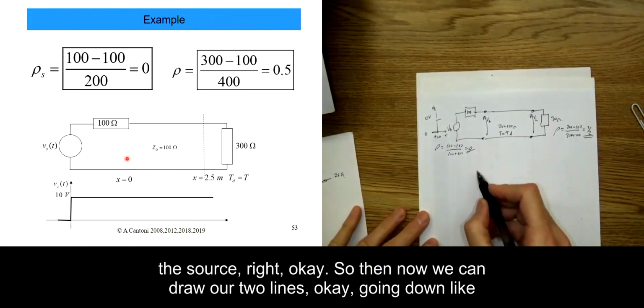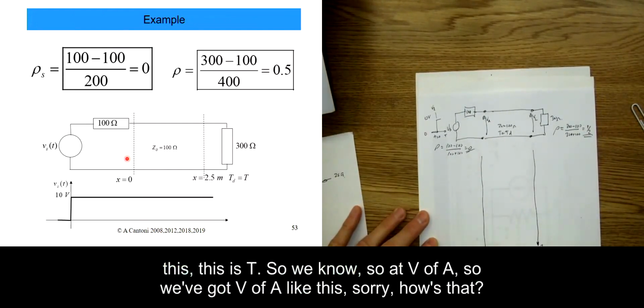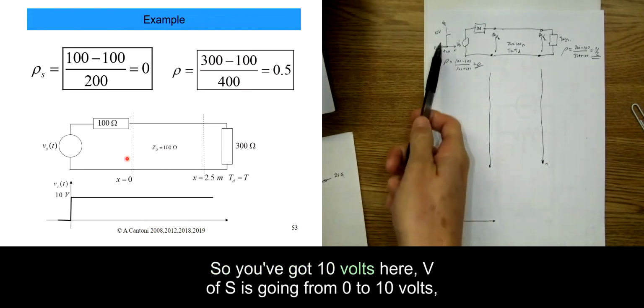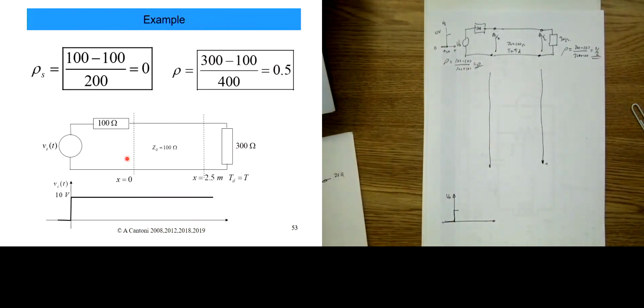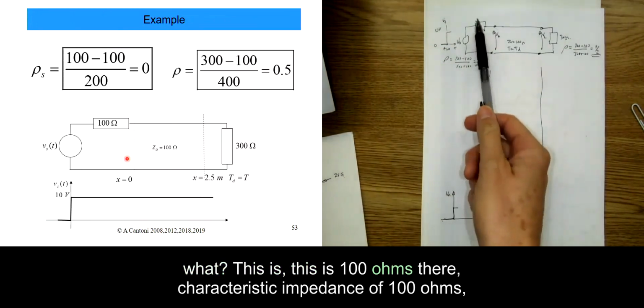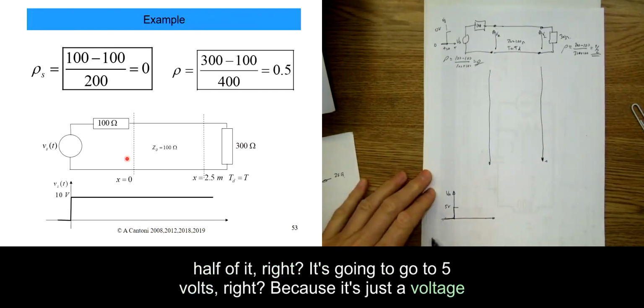Then we can draw our two lines going down like this. This is T. So at V of A, sorry, how's that? Good, tell me, because I can't see. What will be the initial voltage V of A goes to? Someone tell me. V of S is going from 0 to 10 volts. What will V of A initially be? This is 100 ohms there. Characteristic impedance is 100 ohms. Half of it, right? So we're going to go to 5 volts, because it's just a voltage divider.